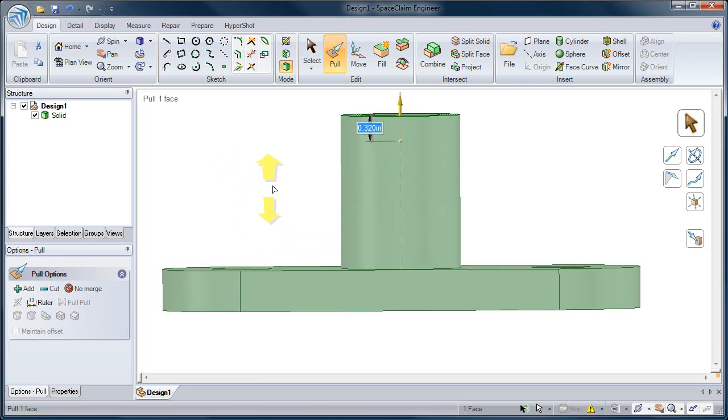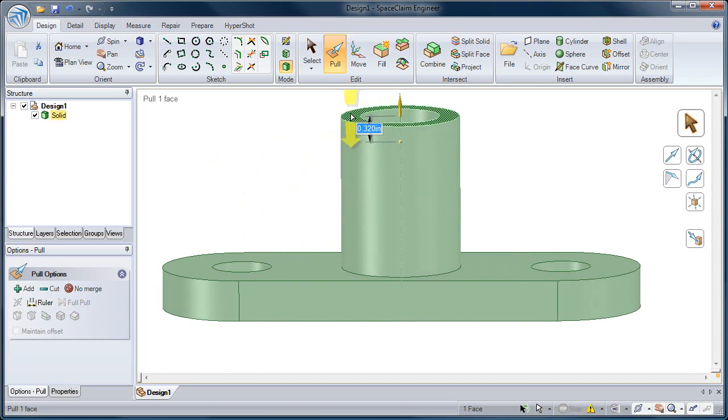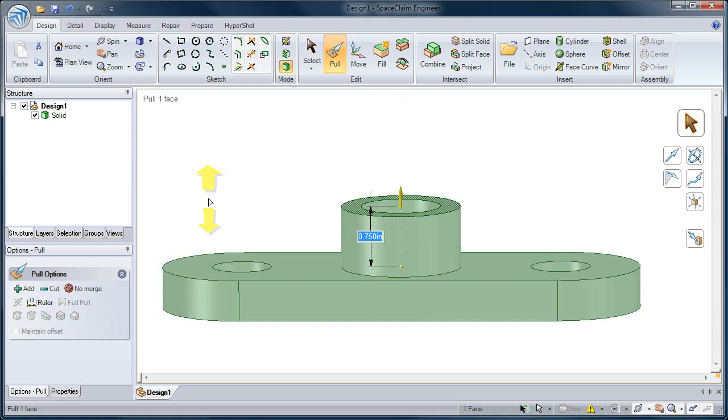But if I was unsure of where that was to start with, knowing that it's 0.32 inches from that location sometimes doesn't help. And so what I'd like to do is probably create a ruler dimension. Remember, that's the same as this button here. And that will allow me to dimension from another location. I can dimension from our upper face or the lower face on the model. And now I can type in a dimension that I might have a better idea of how it affects the model. So we can make that boss 0.75 inches.